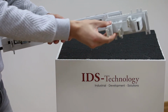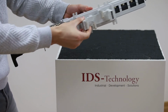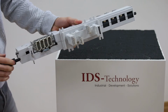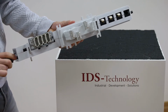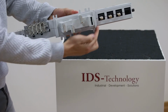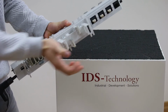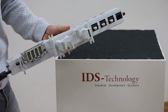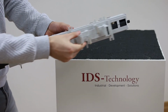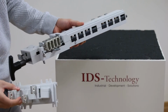This can be followed up very well when the cable module is pushed in its position and turning the shaft again. In this position, the high contacting pressure can be demonstrated. The turnable, spring-loaded and flexible contacting bolts press each other between the contacting module and cable module, respectively the busbar module, keeping all the contacting forces within the system itself.